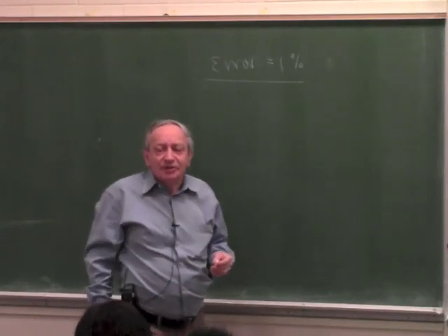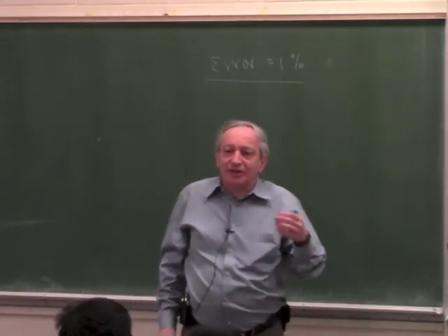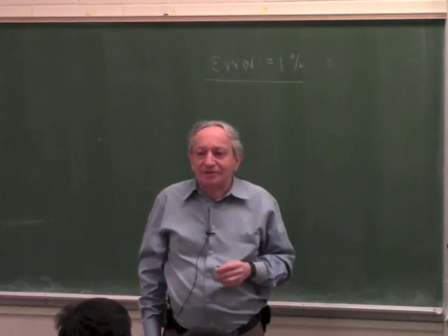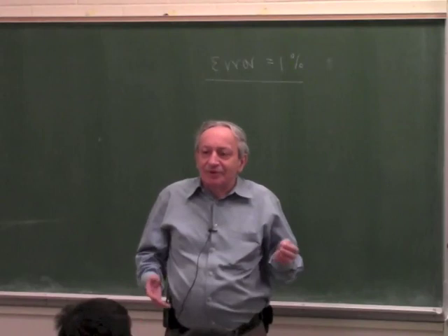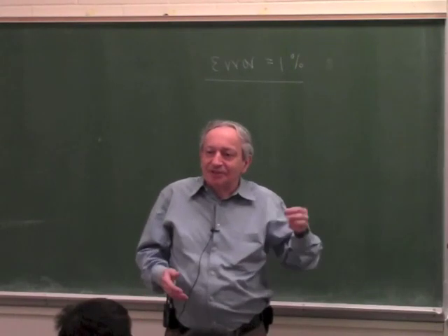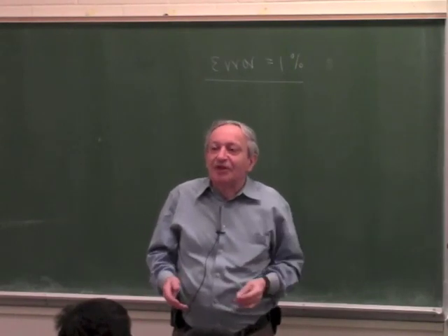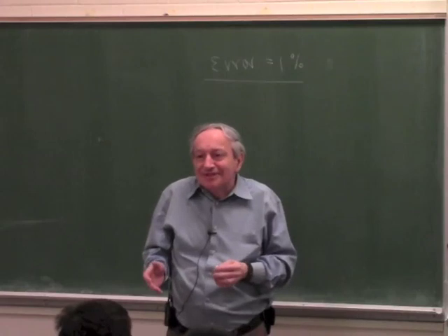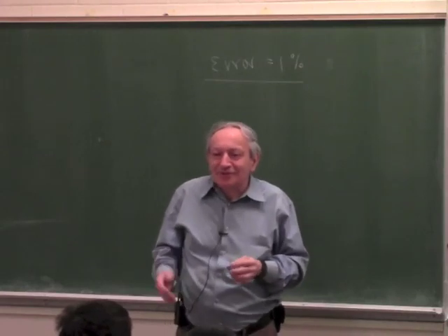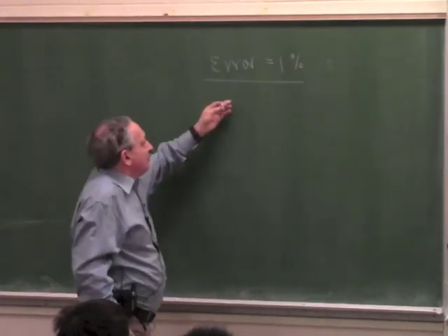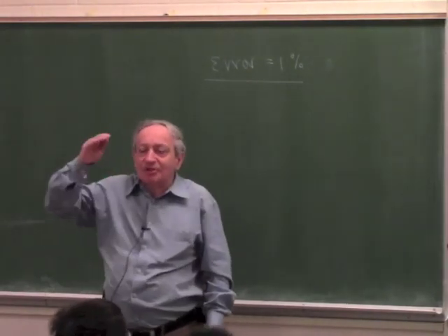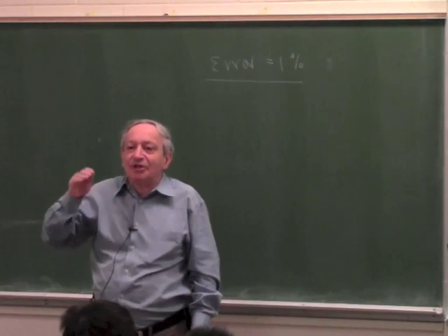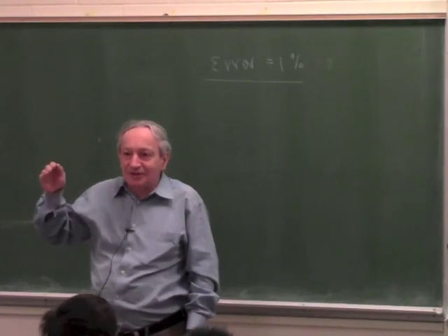So how many bits do I need to have an accuracy of 1 part in 100? 7. 7 is 128, right? 8 bits is 1 over 256, 7 is 128. Now 6 is a bit too low, 64. So typically you say, okay, if I put a 7-bit system, I'm plenty, because I can position myself in increments of 0.8%, 1 over 128, okay?